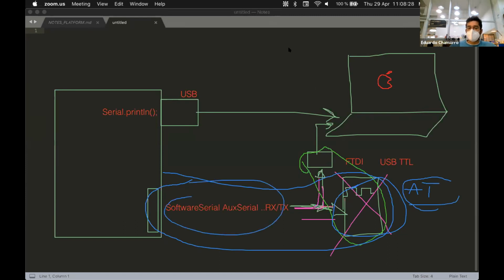Here you have a problem: if you use software serial libraries, as you're not using dedicated pins for serial, they are not as fast as hardware dedicated pins. So you're constrained to slow baud rates. For example, I just checked the documentation of the Arduino SoftwareSerial library. They say it works up to 115,200 baud, but actually it's not true. I know that around those baud rates it has a lot of instability. Actually, it was more like 57,600 and lower.